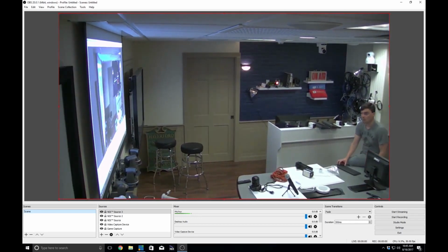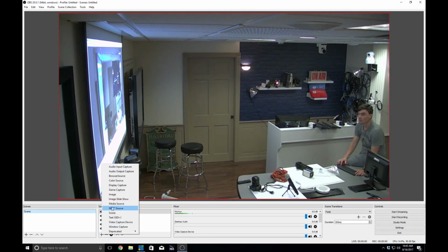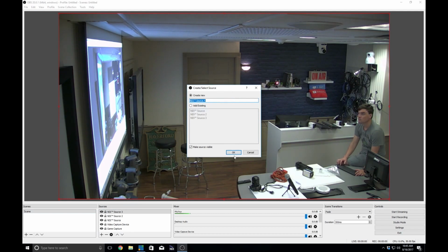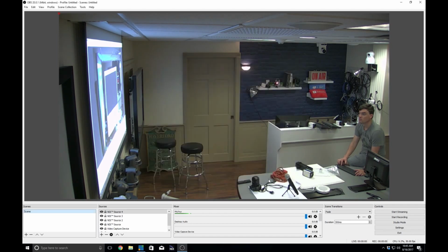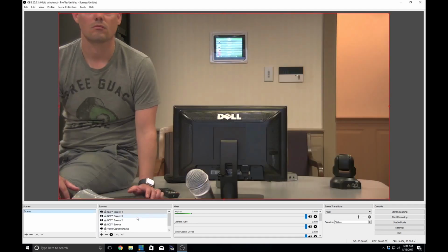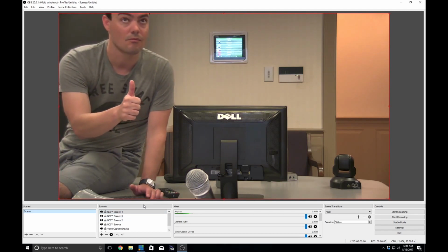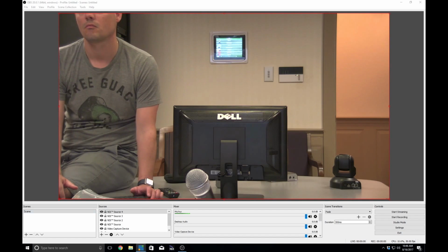But you can see here the NDI video looks great, and one of the things that I love is even when it's panning and tilting and zooming, there's no video tearing. Usually when there's a lot of motion, that's when you might see tearing on like an RTSP or an H.264 stream. None of that. Now again, we're on a local area network, which is one of the ways Andrew Cross is able to work this magic, because he knows exactly when things are connecting and disconnecting, and that's beyond my understanding, but he's able to drop the P frames that are unnecessary, and able to reduce bandwidth and really increase the reliability of the stream so that it looks as if it's an SDI stream.